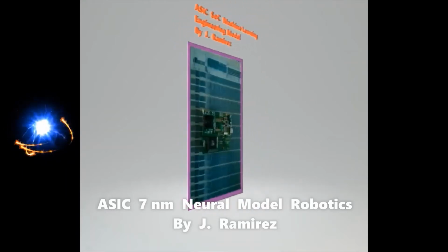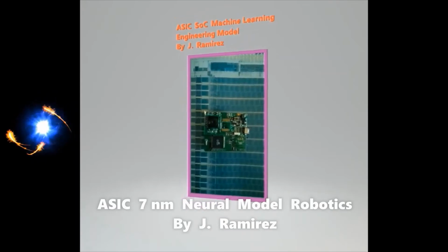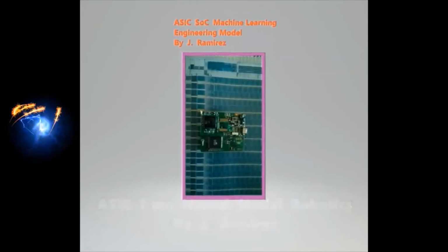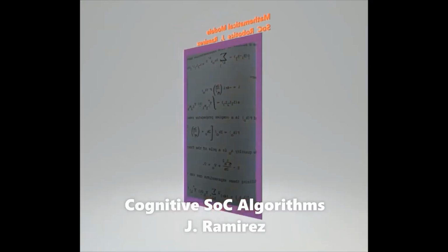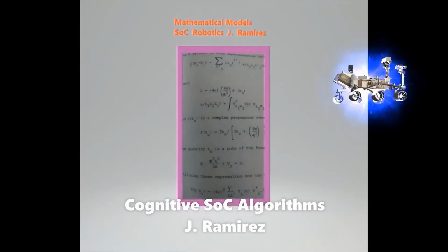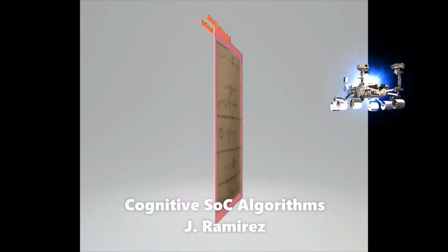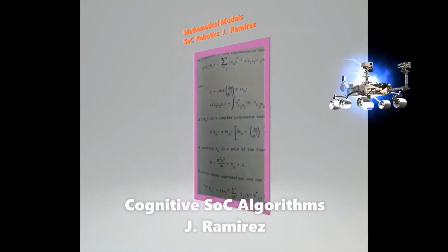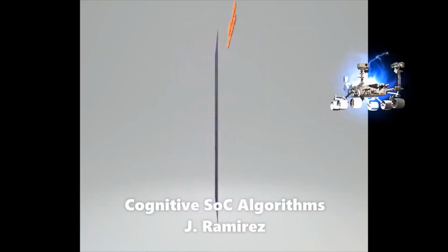After the final transformation was done, the clock splitter was pulled from the macro and the two LSSD clocks were reconnected between the splitter and the latches, therefore partitioning the design in two areas.